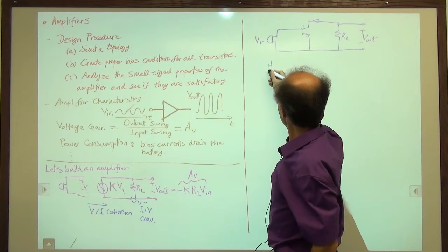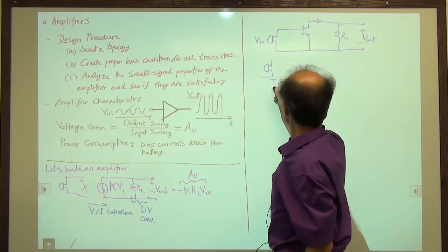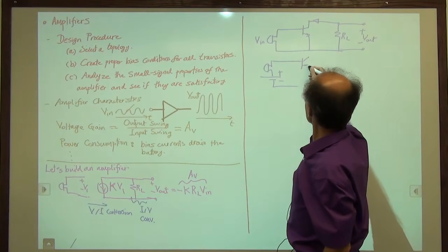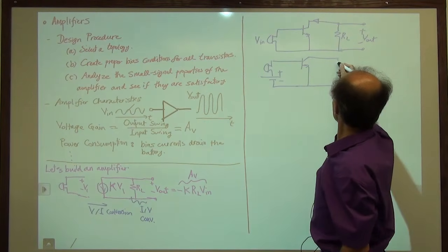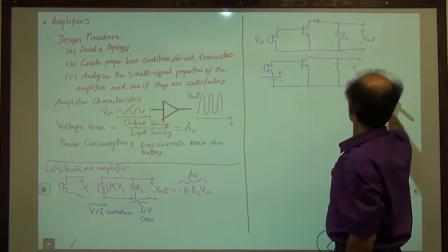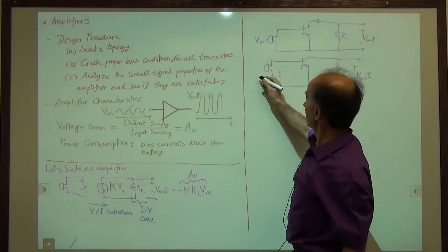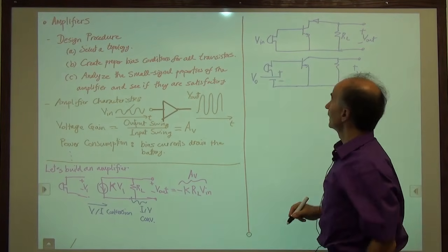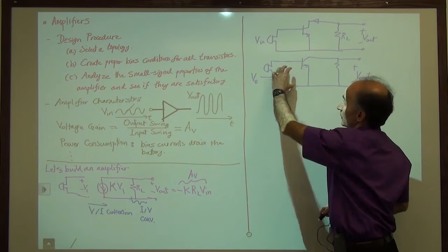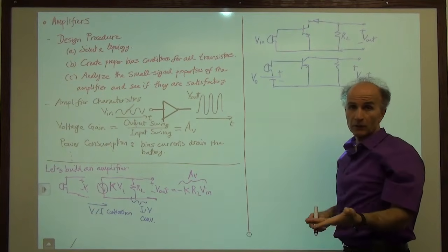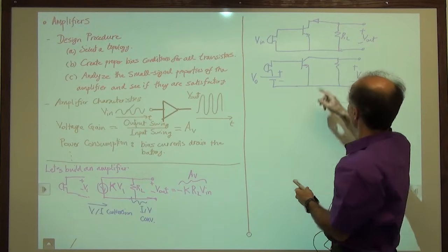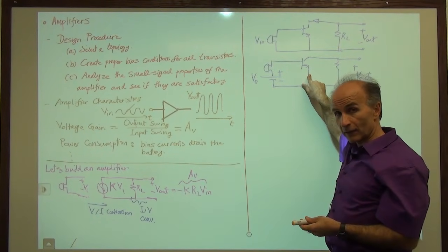So in the next step, that's what we did. We added a battery here, and then we went to the bipolar transistor, and then we came to the resistor. Our hope was that when this battery is connected to the base emitter, which we call V0, even when the microphone signal is 0, the base emitter voltage is equal to V0. V0 can be chosen to be some reasonable number, 700, 750, 800 millivolts, and that will give us a certain bias current in the device.